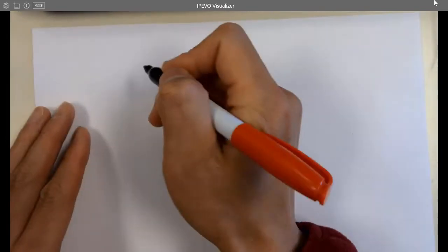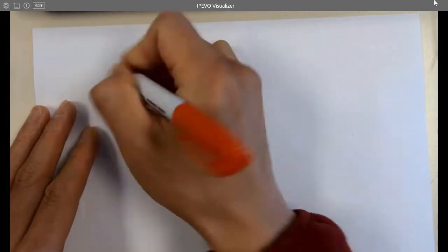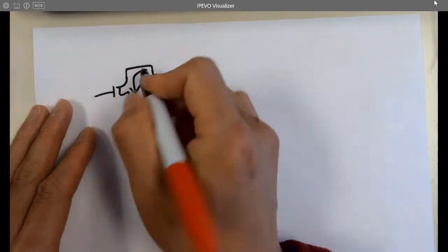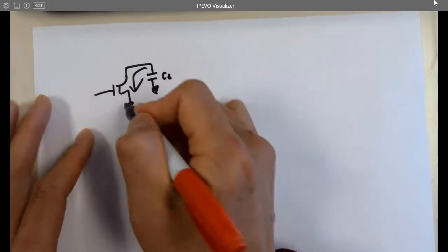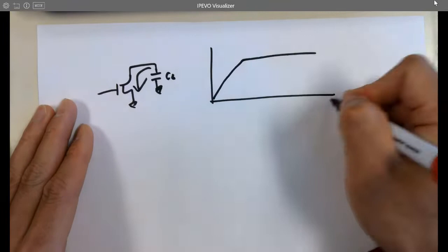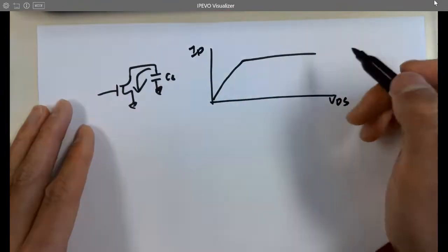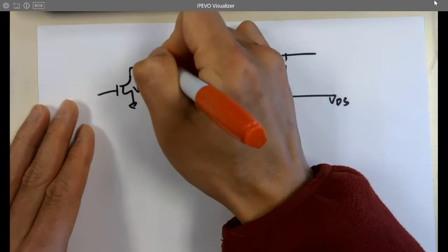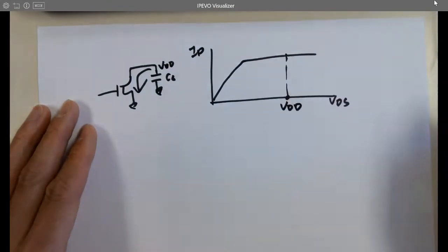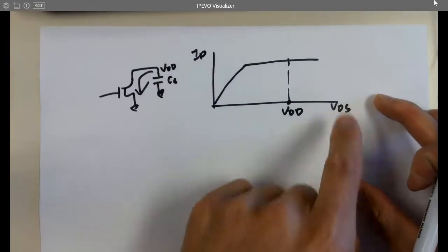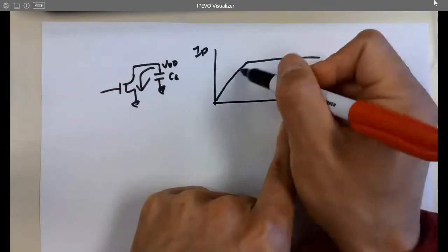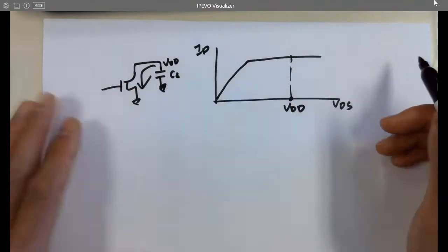All right. And we know that as an NMOS, when it discharges the cap, this is a C load, okay? It discharges the cap through that channel and it follows a curve, because this is VDS, this is ID, right? That's a curve. Originally, if this model stores VDD over here, VDS originally equals VDD. That's the original value. And when we start discharging it, it follows this curve. That's the IV curve of the transistor. It's going to follow that curve, definitely.